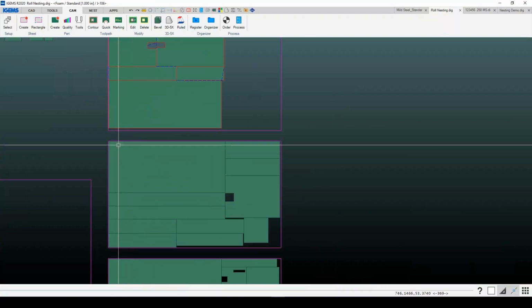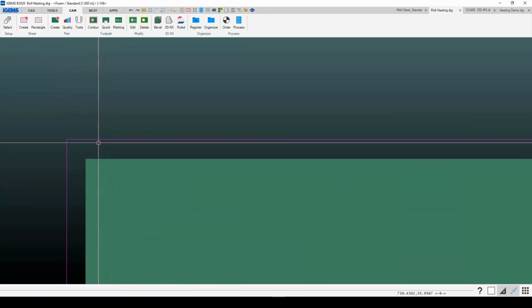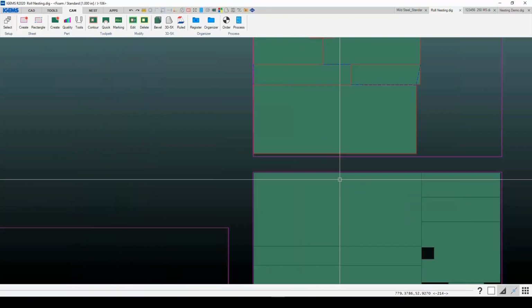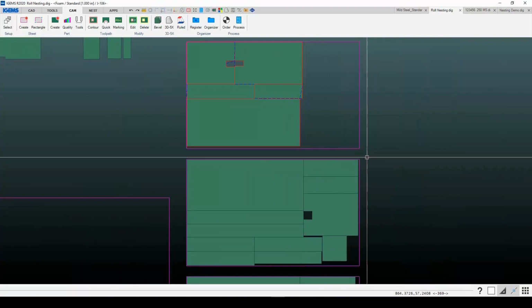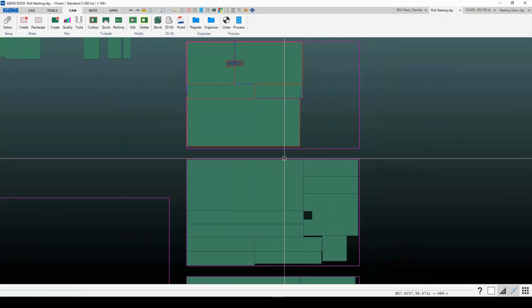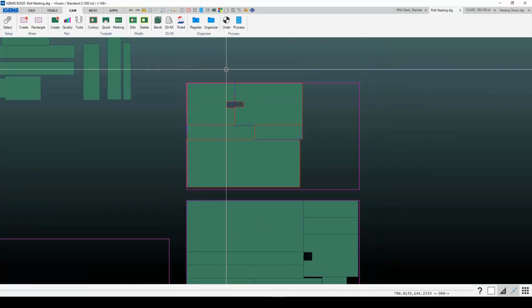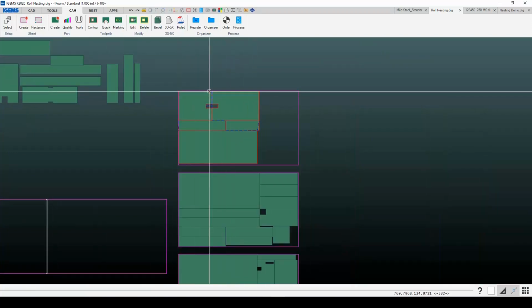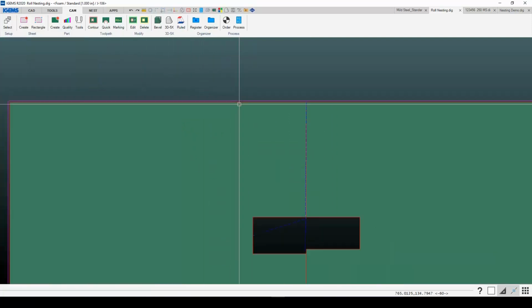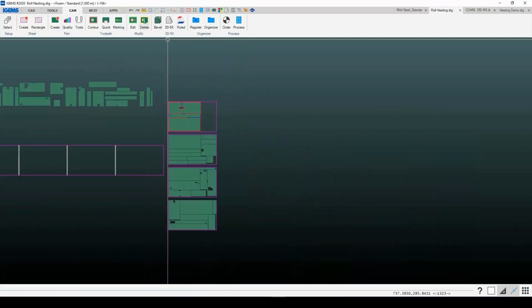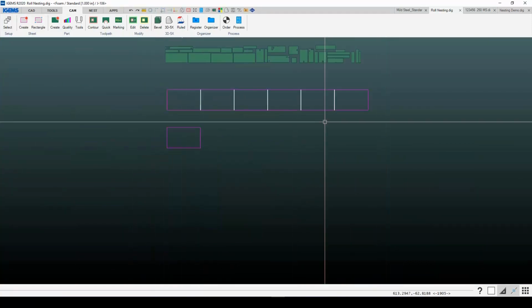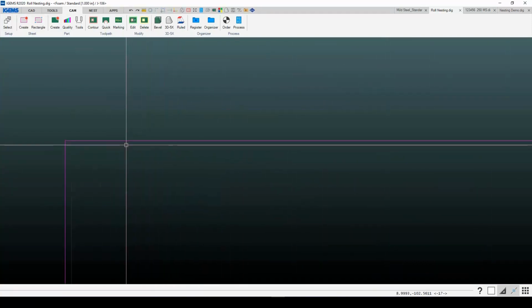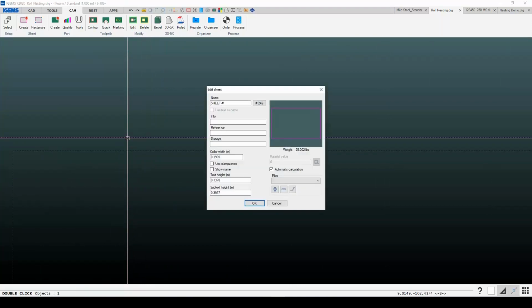So this one here, we've got a little bit of a gap here. If you can put your material on there because you have a fixture, or like that video I was showing you where it has a guide that's going to guide that material in, you can actually nest it right up against the edge of that sheet of material and use that as your raw edge and not have to do this cut that's along there.